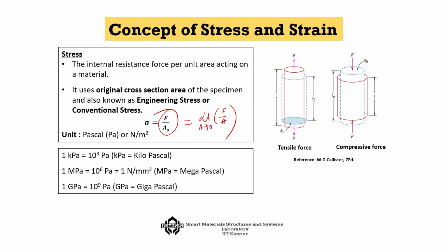So, that then becomes the stress, and usually we represent it in Newton per meter square, but during our talk we will go to kilopascal, megapascal and gigapascal pretty often. I do not define it each and every time, but you can see what that means: 10 to the power 3 Pascal for kilo, 10 to the power 6 for mega and 10 to the power 9 for giga.